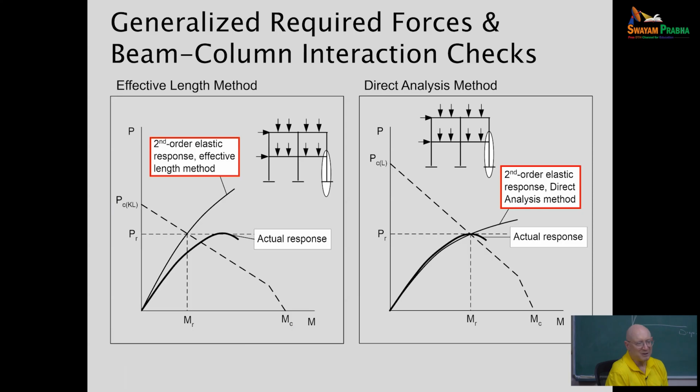Now with the direct analysis method, this is where I say it is a poor person's test simulation. Saying, hey, I really don't have the time or the capabilities to do a distributed plasticity full nonlinear analysis. I'm trying to design this frame and my phi isn't that big. Can I do something fairly coarse that gives me a coarse representation of what's really going on in the structure?